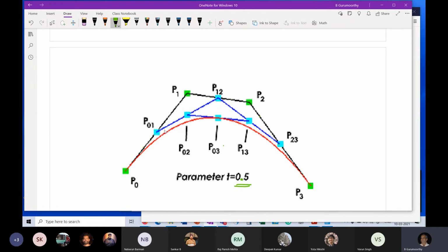And then on that line 0.25, on this line 0.25, and then on this line 0.25, and you will get the point on the curve corresponding to u equals 0.25. Right? So this becomes a very powerful way to generate points on the Bezier curve. See, that's what you have done by doing how many linear interpolations? 3 in the first step, 2 in the second step, 1 in the last step. So 6 linear interpolations, and you get a point on the Bezier curve.